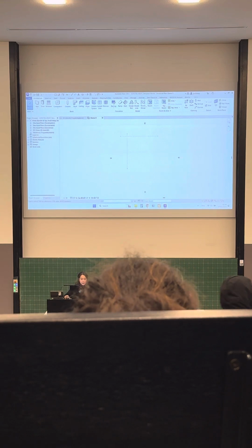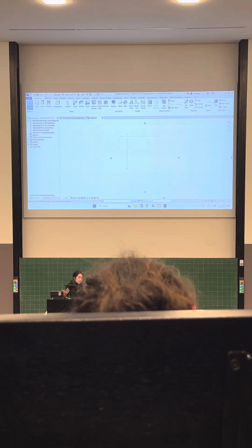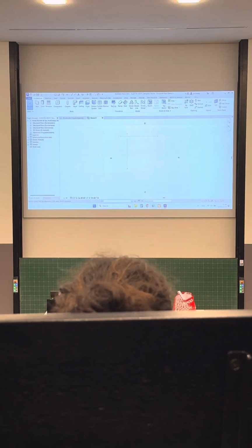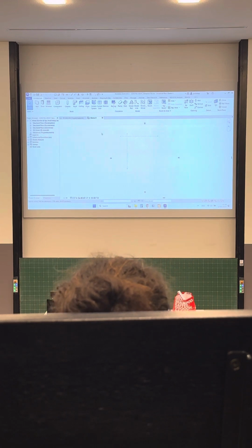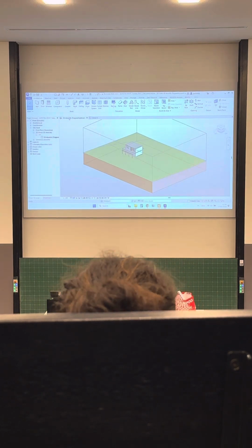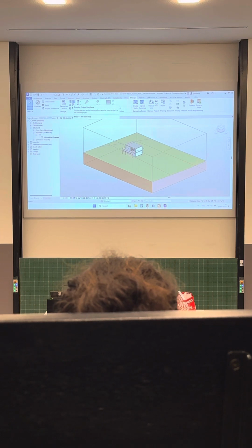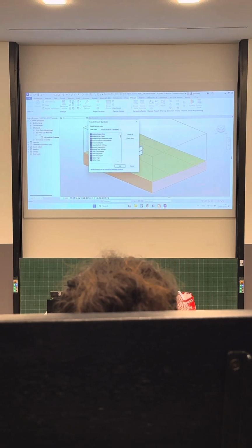And this RTE file basically has standards, so depending on which company, on which project you are working, there could be different standards. So we are just presuming that this is the standard that we need. So we're going back into our RVT main project, and we go into the Manage, and there is such a button in the settings, which called Transfer Project Standards. And you basically transfer here the information that you need to take from your template.